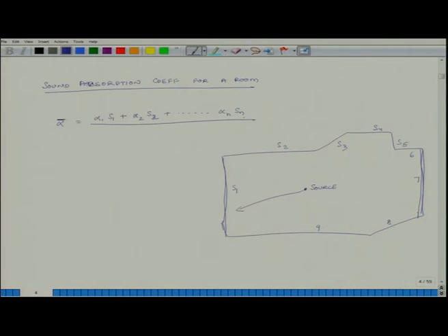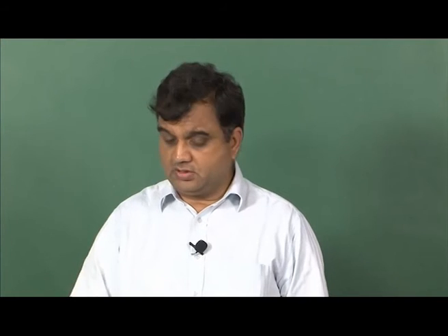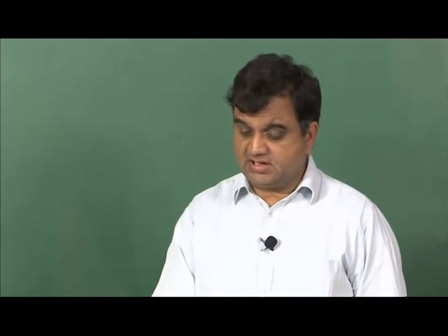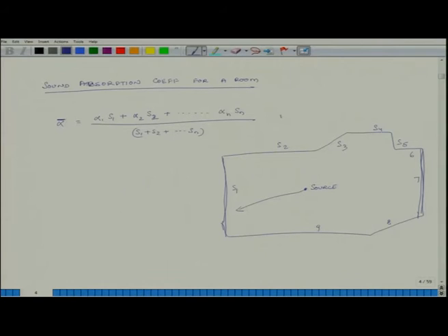Okay. So, this is a sum of all the multiples of all absorption coefficient and their respective areas divided by the sum of areas. Okay. So, that gives us average absorption coefficient for the room, and this is for the case when there are no people.